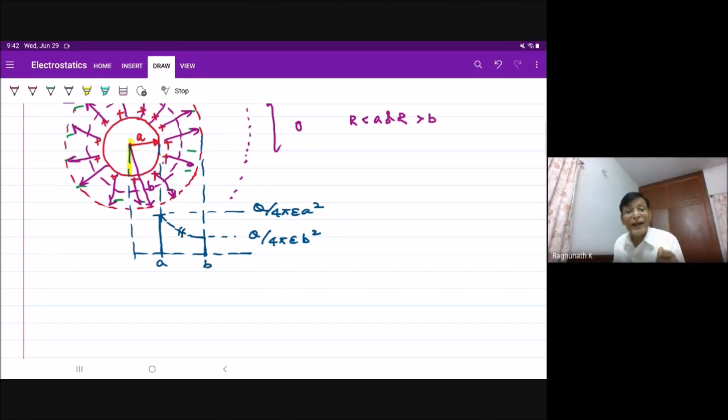You know that at every surface charge, there should be a sudden change in the flux density, and hence the field intensity in the perpendicular direction. What is the amount of change? Change is equal to the magnitude of the surface charge.